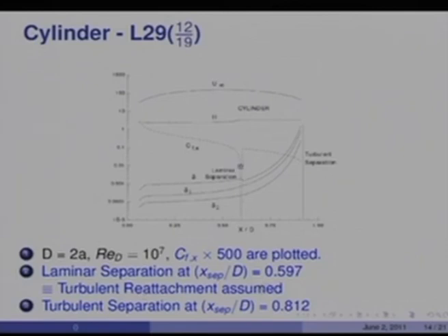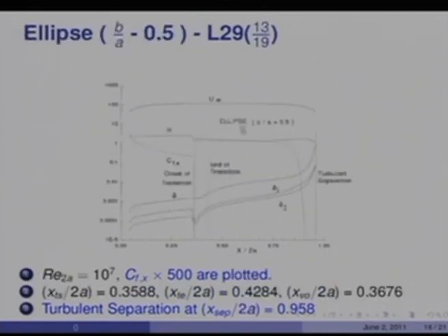So, in other words, the transitional length is simply absent here, and you simply begin the turbulent calculations immediately after laminar calculations have yielded Cfx going down to 0. Very interesting phenomenon. No transition at all.